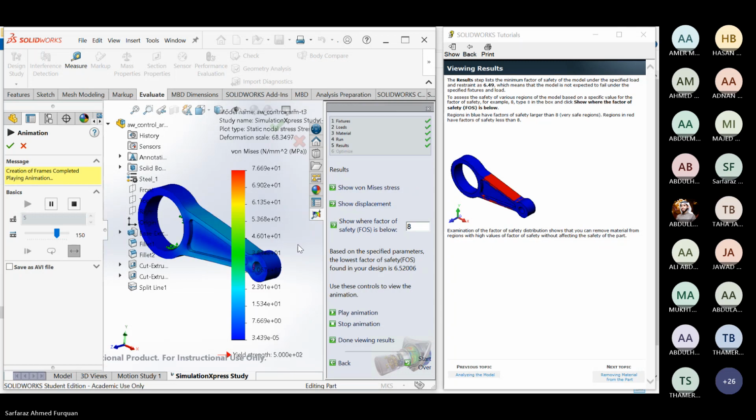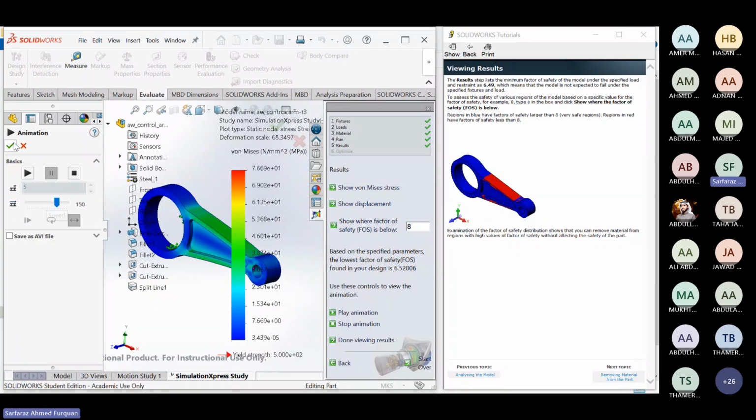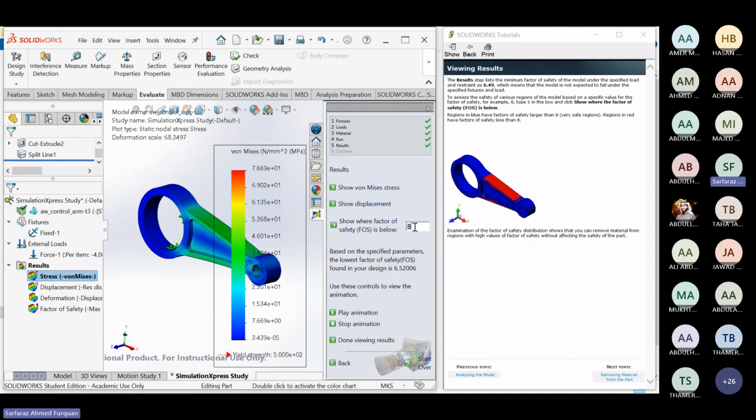So if you take a factor of safety 8, then this value would be closer to this or slightly above this. That's why it is getting red and is indicated as critical region with that high factor of safety value of 8. Okay. Something around 6.49 or between 6.5 to 8 is good, or we can say 6.5 is safe. Anything close to 8 is going to have some kind of deformations there, which is above the safety limits.